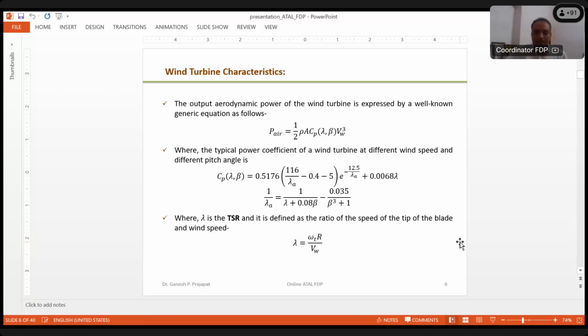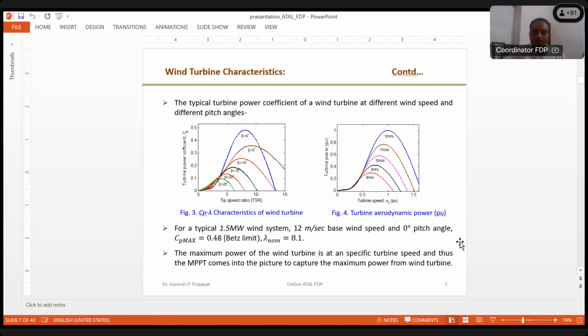So these are the wind turbine characteristics. Now if we draw it, here you can see the drawing of the turbine power coefficient. Although these are again conventional, we should discuss these two curves here also. Here this one is the turbine power coefficient with respect to the tip speed ratio. One can think of the pitch angle as 0 degrees. Pitch angle means the angle made by the blade orientation with respect to the flow of wind.